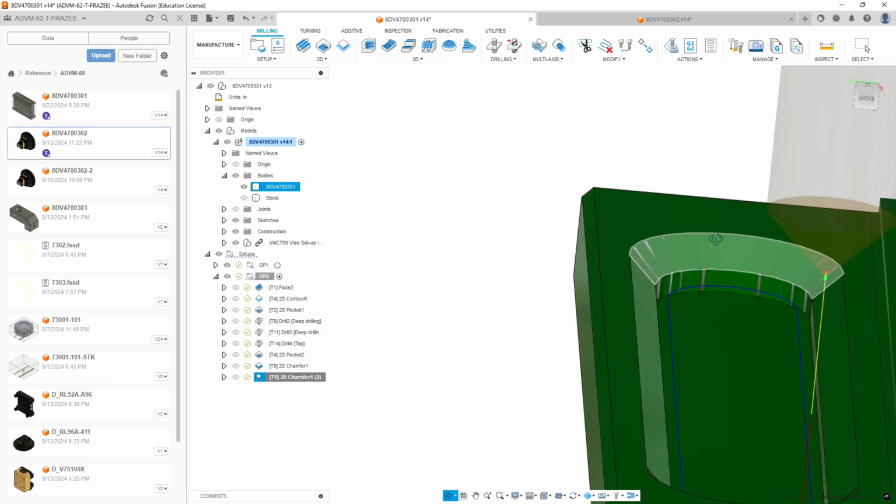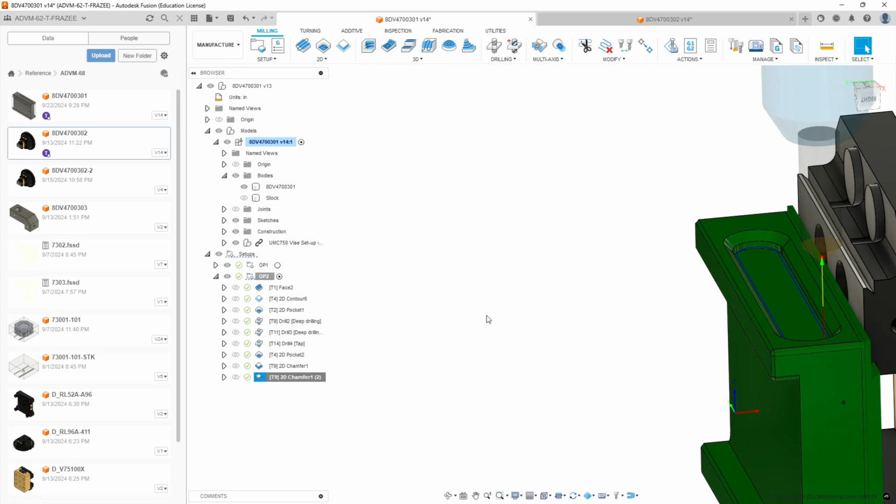Now that's going to be taking that all on one pass. It's a lot for it to take off. It is what the cutter's designed to do. Unfortunately, Fusion doesn't have an easy way to do this in steps. So for a larger chamfer on this, it's a fair amount of material to remove. And there is a way we could array it up and do some shifts and then copies to simulate doing a multiple depth cut. Unfortunately, it's not canned and it doesn't just automatically do that.